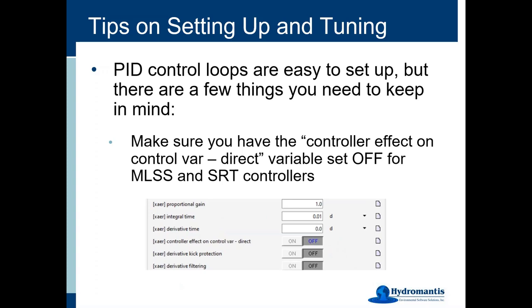And you have to make sure that you have your control effect on the control variable set in the correct direction. Otherwise, your controller will move actually in the opposite direction that it should. And usually that's a really obvious thing. When you run your simulation, your controller won't work at all.